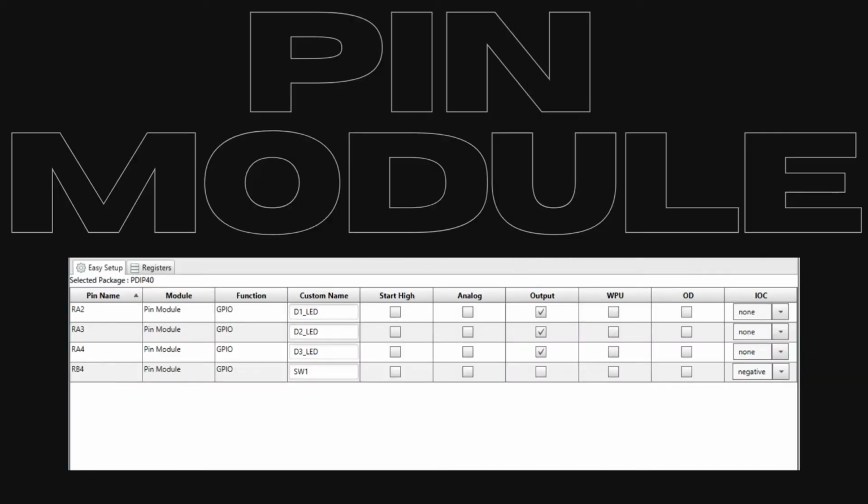After finishing the Pin Manager, click the Pin Module selection in the Project Resource section. The center section will show the Pin Module settings. It will show both RA4 and RB4 listed on the I/O chart. Number 1. The RA4 pin will be an output and control the LEDs. Click on the output box to make the pin an output.